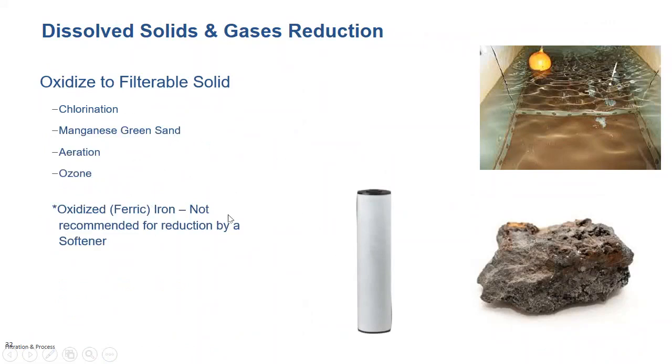What we mean by this is iron reduction by cation exchange has reasonable practical limits for which we do that. Why? Iron can be much more tightly held inside a bit of resin and have a very hard time coming off.